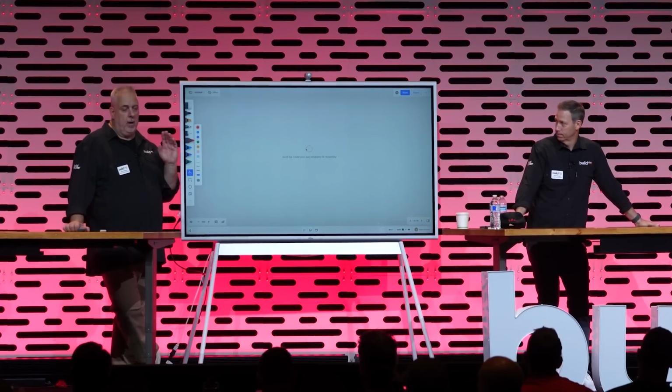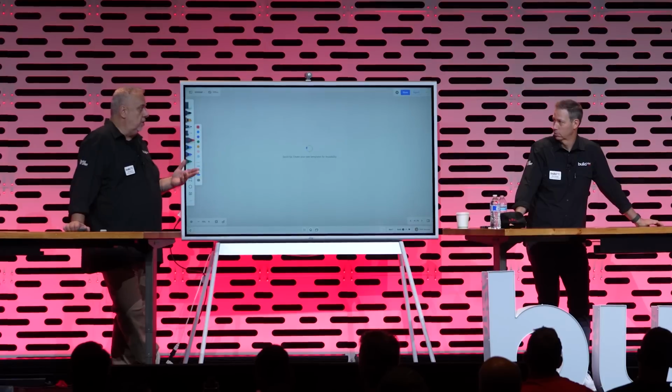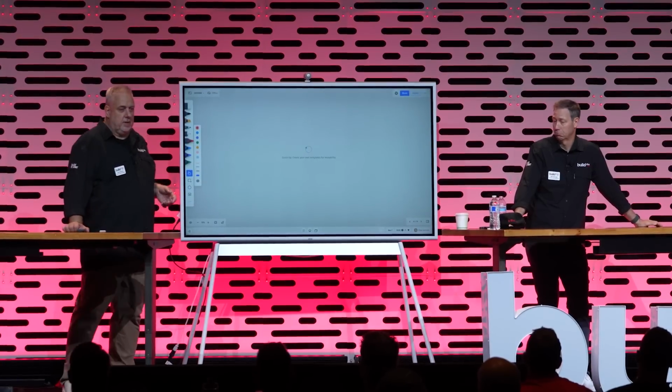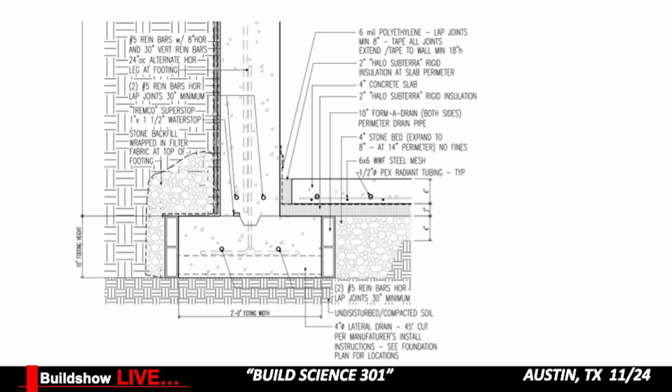If we do, we want to make sure that that insulation is an unfaced air permeable insulation with the drywall. Drywall is a really good air barrier, but it's pretty much vapor open. I forget, I think it's like 300 perms or something. It's like drywall, vapor goes right through it. So some of the details.